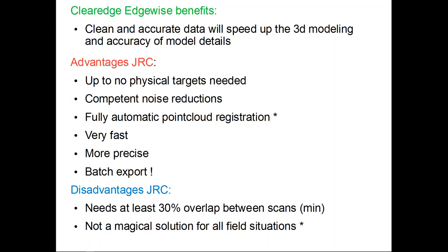Before, in order to deem a result of a registration acceptable, we would have had targets like 5 mm deviation. That would have been the maximum accepted deviation. But sometimes if you looked at 2 point clouds, you could have seen that they are very little, almost unobservably, offset from each other. Now when we look at the scan data, we see interference patterns as the point clouds are merged within each other, which is an excellent result.